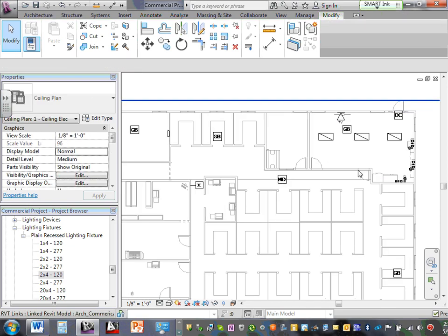A fixture needs a switch, right? Let's go switch that baby, huh? Yes, sir. Okay, but hold your horses before you do anything. Would the switch be in the ceiling or in the floor? So you drop the fixture here and you move. You can't believe how many times people get confused. The only thing you drop in that view, guys, is anything in the ceiling. A switch is not in the ceiling. Did you guys drop 3? Everybody drop 3? When you drop 3, move, get out of there.